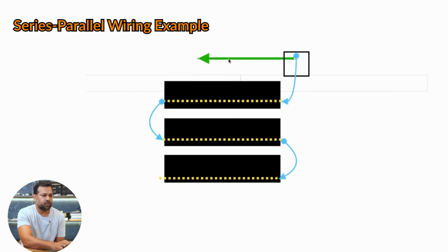If you had to do it that series parallel way, it would look like this. So this is your parallel wire going back to your power supply and then to your switch. This is the low voltage. Well, I shouldn't say low voltage, it's all low voltage. This is the smaller wire gauge going into this LED at this level. Then the end of this one powers up this one. And you have to do this type of installation if you're doing a DMX installation like those stairs I showed you. That's how the installation has to be. It's going to be like a daisy chain happening.